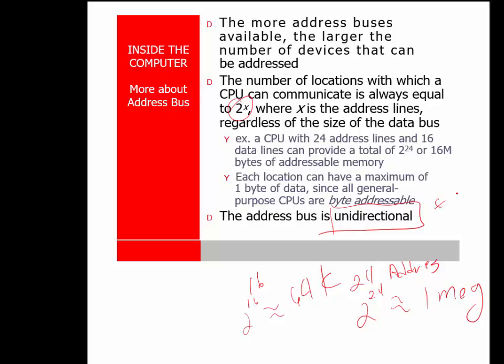So this is not 100% true, like a lot of statements you see in this book or any book when we talk about microprocessors. The reason is this book was written 10, 15 years ago. Lots of things have changed. Just like ROM, I mentioned that we have ROM devices that we can rewrite today. I have a motherboard that's 6 or 7 years old, and a new type of monitor or graphics card comes out, and the hardware is there, but the software in the motherboard's BIOS doesn't support that. They can issue a firmware update and update the ROM in the motherboard.